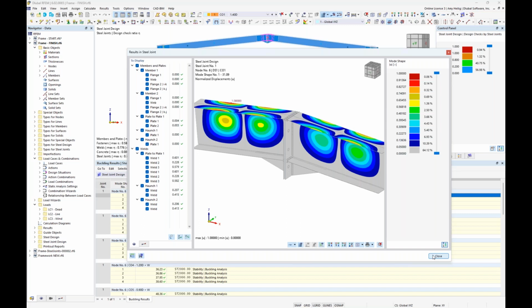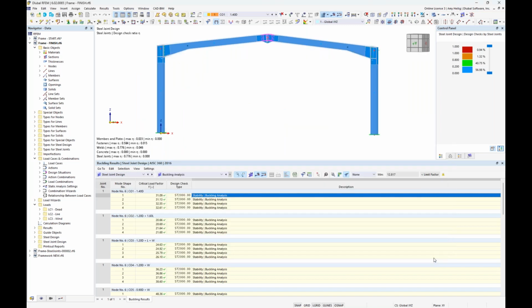So we have the ability here to carry out this additional analysis and determine, if buckling is a concern, do we need to increase the thickness of these surfaces, such as the web members or flanges, or maybe we need to add additional stiffeners with those component input options.